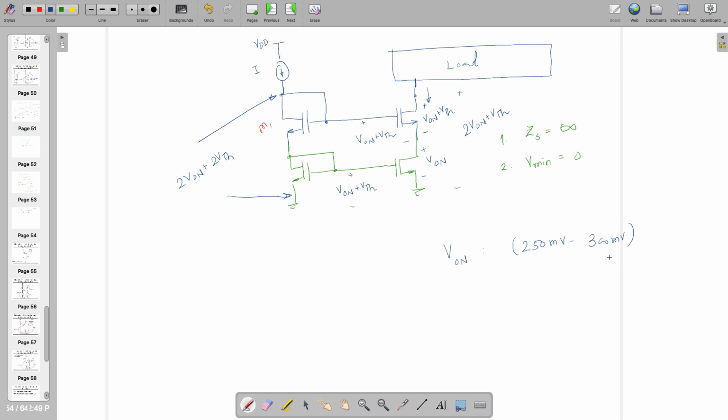So now we learn that the simplest one is good in terms of minimum voltage, but on the source impedance side, it's not infinite, it's R0 only. And in the case of this one, which is folded cascode, it's gm times RO square. So in that case, of course, cascode is the winning one. However, in terms of minimum potential, this is not the minimum voltage.